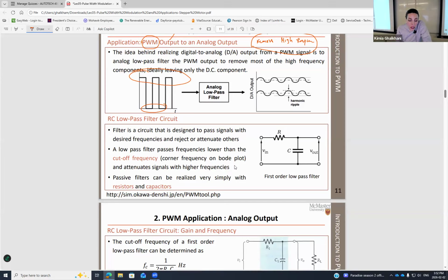And then if we have a continuous signal and we are using the method of successive approximation, remember we had it in analog to digital, and that method inside the compiler, the microcontroller, we don't do it manually. It's doing its job. Method of successive approximation means that sample and hold being connected to the converter, each time turning it to 1 and 0 until we are closer to the input. Remember that? I explained it.